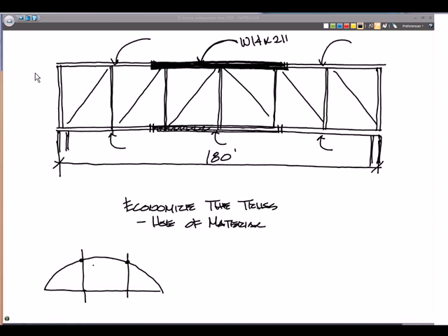But just to make a point, now, if the rest of the truss doesn't need to be that heavy for the top and bottom chords, we want to cut down the amount of material. We don't want it to weigh 211 pounds per foot. But we want it to be in the same family as the W14, so it splices together nicely.